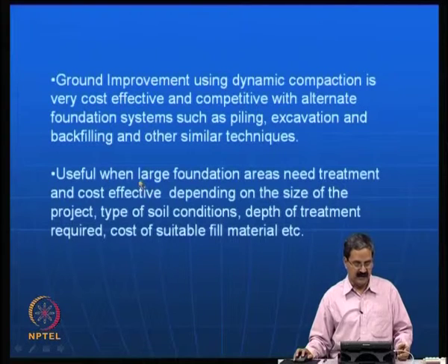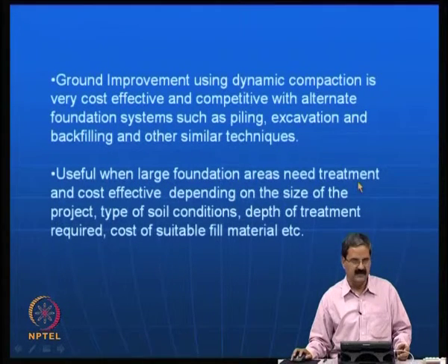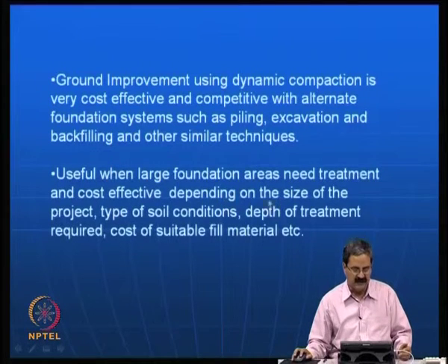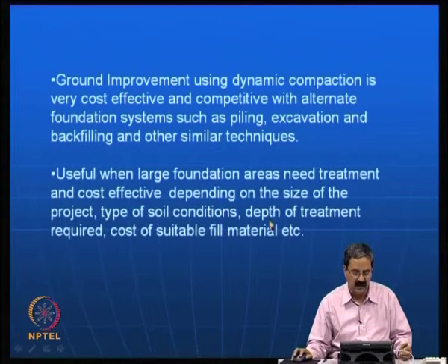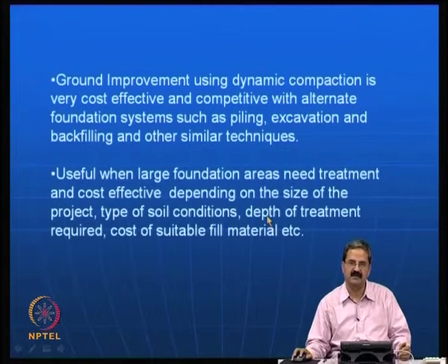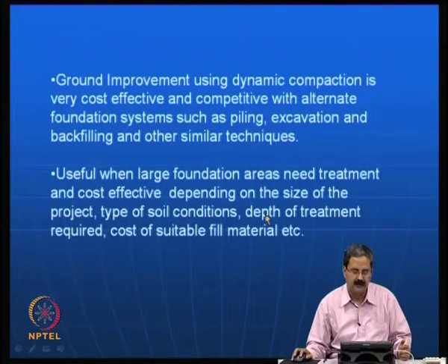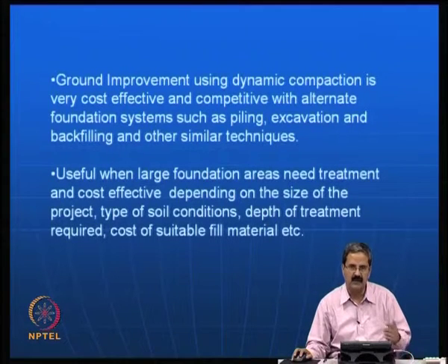So, particularly this is very useful when you are trying to handle large foundation areas, say for example coastal areas. They result in cost effective solutions, because depending on the size of the project and the type of soil conditions, say for example as I just mentioned, the techniques of dynamic compaction, the range is quite big, right from municipal solid waste to sands it can take care, and the cost of suitable fill material is also important.